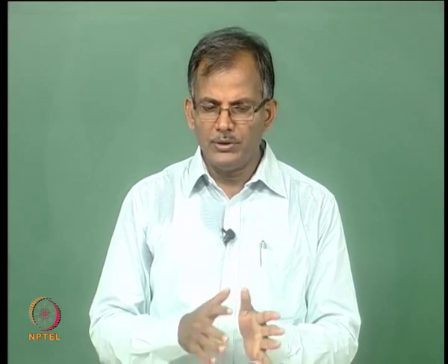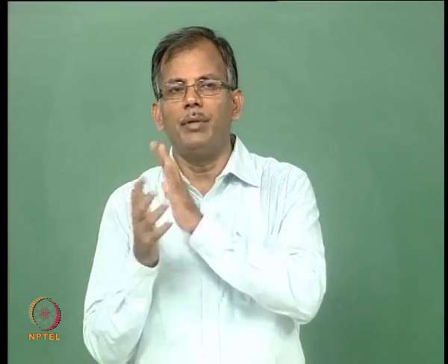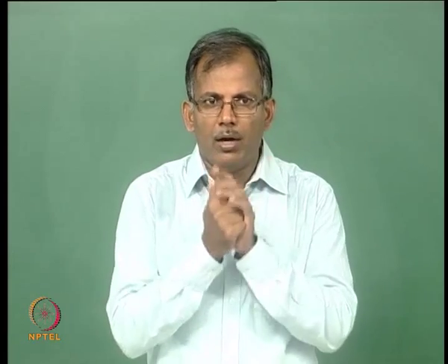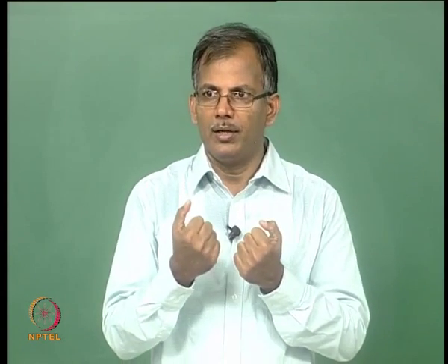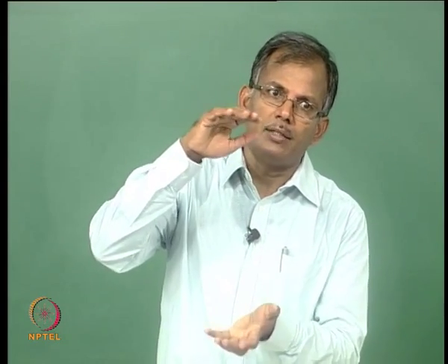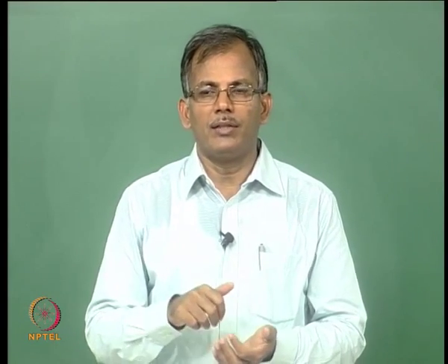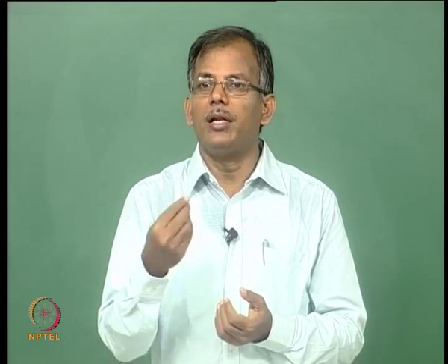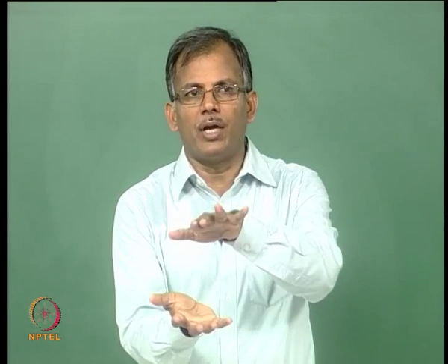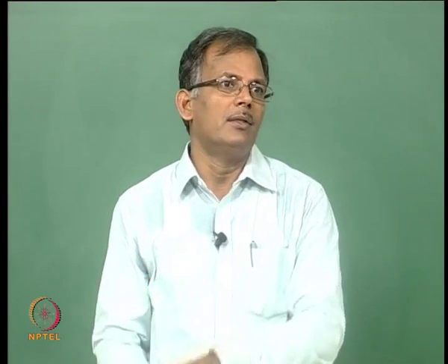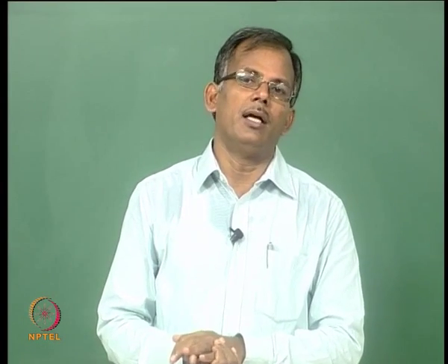So what happens is during the process of dynamic loading, the p-y or the load displacement relationship gets weakened very much higher at the surface level, whereas when you go down below the seabed, the disturbance is less. I think that we can easily understand. When you have a stick moving back and forth or a pile moving horizontally, near surface soil will be disturbed more than the soil at the bottom.